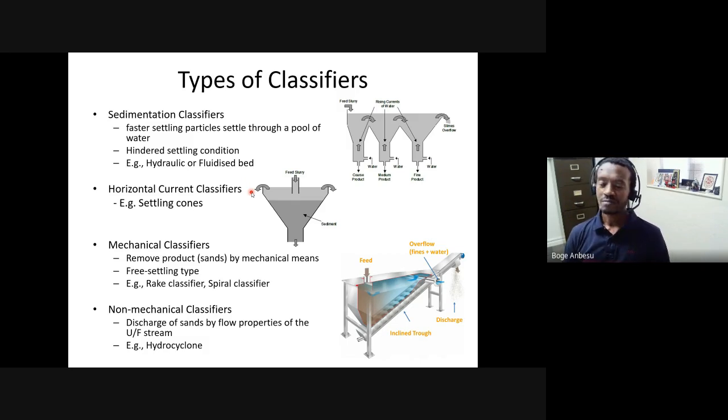This can be operated in different ways. For example, you could use it purely for wastewater treatment, or you could use it for other applications. In mineral processing, we use thickening, which is a process where we go from a low percent solids pulp to a high percent solids pulp. The way the thickener works is simply by allowing particles to settle and then be recovered as a discharge at the bottom of a cylinder.